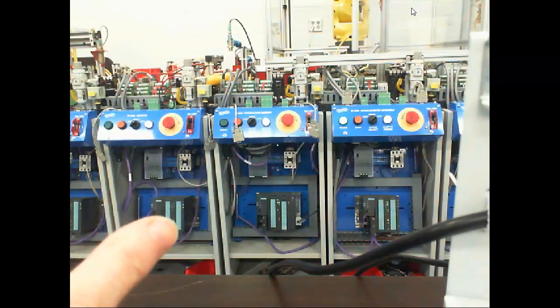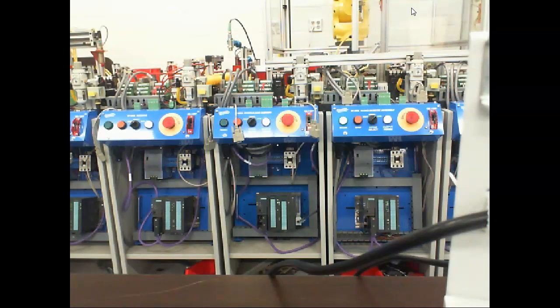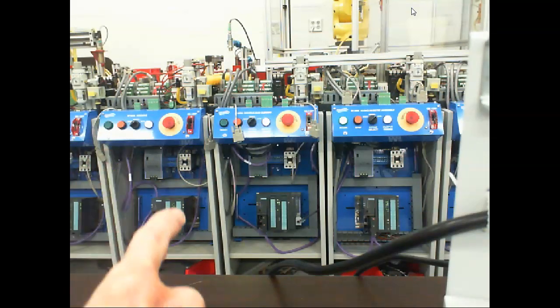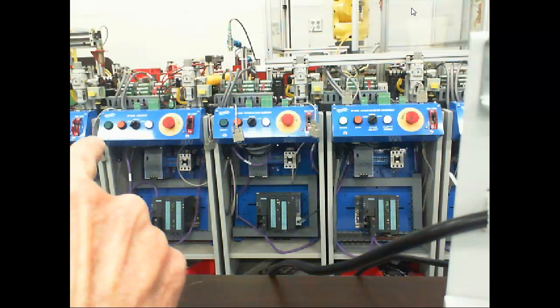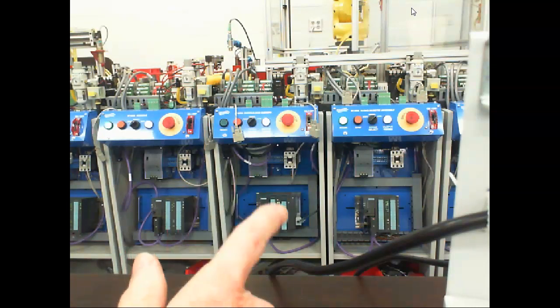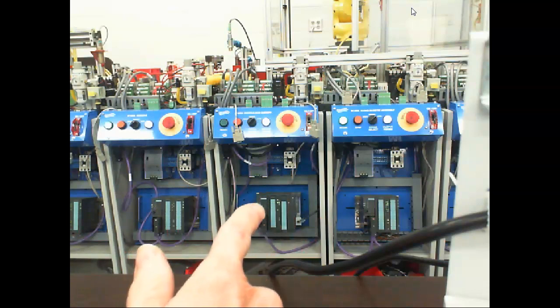And so these are the PLCs. These are Siemens 314s, and we'll talk a little bit about those. Also they help us troubleshoot with all these lights that are going on right here. You can see this light right here is blinking, and you look up here and you see this is blinking. Well, this is controlling that. So if I come over and see this blinking, and then this right here is not blinking, odds are we've got a bad connection between the output of the PLC and the device itself. So PLCs also help us in troubleshooting a lot by just reading the status of the lights on the front of these things.